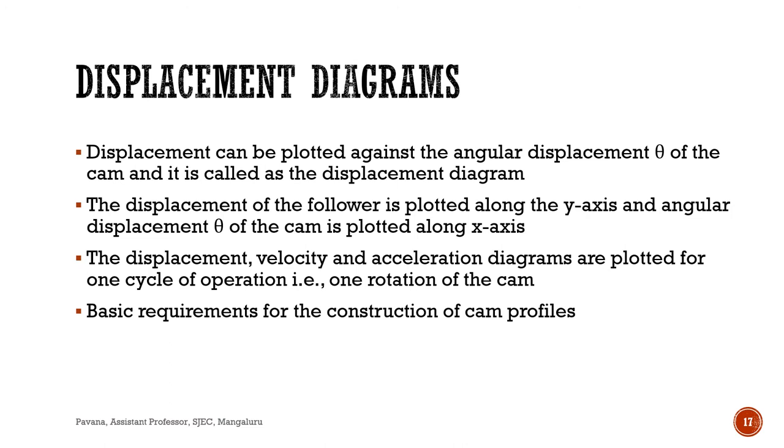So this is the basic requirement for any cam profile. If you want to draw a cam profile, the displacement diagram is a must. Whatever the shape of the follower, it may be knife edge, roller, flat faced, or spherical follower, but the displacement diagram remains the same. It depends on how the movement takes place with respect to the angle. So that is very important to draw a cam profile. That is the displacement diagram.